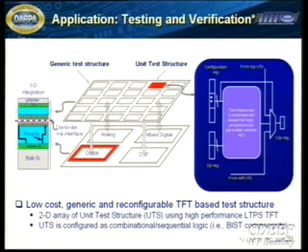Some of you might be familiar with built-in self-test. Some of you might potentially think of having on-chip oscilloscopes. Or one can potentially measure the speed of certain sections of the circuit and so on. So it's almost like having an on-chip tester that one can think of, right, in that TFT. And these are scaled devices. They're certainly not down to 50 nanometers or so, but in 200 to 250 nanometers, I can really think of having, on a glass substrate, a bunch of unit test structures.